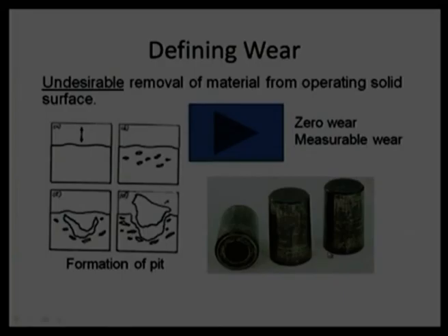Let us see this roller surface. These are roller surfaces. We are able to find some scratches, some deformation of the surface, or we can say it is losing some dimension, some tolerances. Quite possible that this scar may be 20 to 50 micron, and a 20 to 50 micron change in the dimension of tribo pairs means a lot. It is going to change the performance from one domain to another, from full film lubrication to mixed lubrication to boundary lubrication, with a huge variation of coefficient of friction.